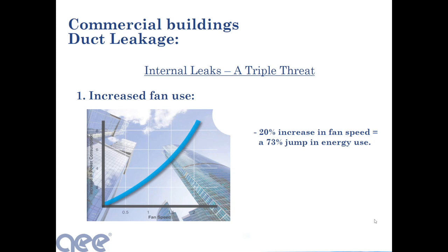The first thing is those fans run longer. Okay? We know from ASHRAE that 20 to 60% of the HVAC operating cost in most commercial buildings is to run the fan. 20 to 60%. So if you're short cycling your HVAC system and causing the fan to run longer than it should, you're going to rack up a huge expense. And the question is, why is that happening?